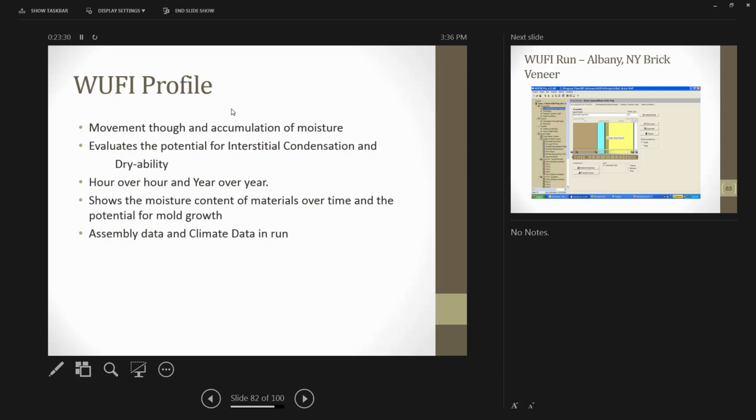I just mentioned building failures. It's not necessarily just having moisture in your wall. I think a great number of wall assemblies have moisture in them, but it's the accumulation of moisture. If you have the potential for that bulk moisture to form, it's not necessarily going to degrade your building. It may, depending on the type of insulation you use, decrease your effective R value, but if that wall cavity has the ability to dry, it's not necessarily going to be a detrimental effect.